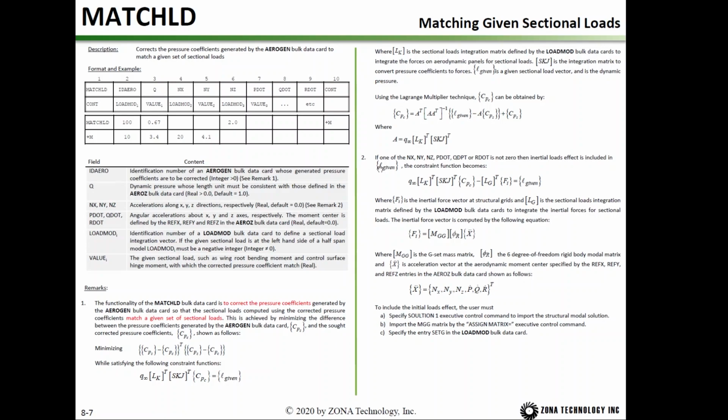Match LD. In case you have wind tunnel measured component loads, and you want to use these component loads to further adjust the ZONAIR computed CP. After you adjust the CP, when you integrate the CP, it will agree with the wind tunnel measured component loads.